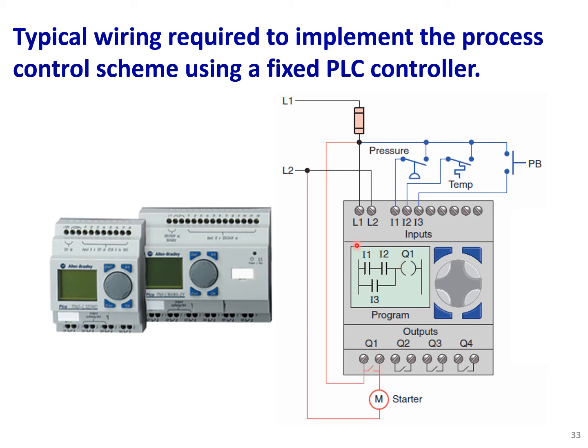Okay, what do we have inside the memory? We have our program based on the ladder logic program, and you see that when I1 and I2 both of them are true, then Q1 will be true or on, or alternatively, if I3 is on, Q1 will be on.